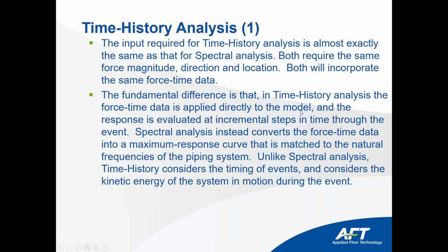Time history is more realistic because it applies the forces as they happen in time. As a difference, spectral analysis instead converts the force time data into a maximum response curve with a maximum factor of 2, which is matched to the natural frequency of the system. Unlike spectral analysis, time history considers the time events and considers the kinetic energy of the system.